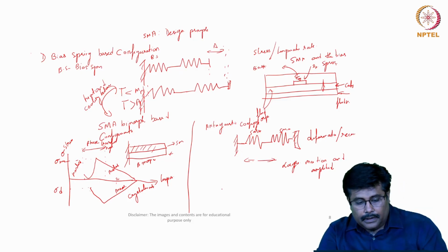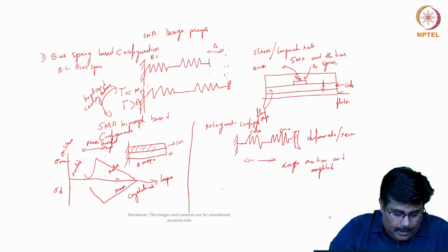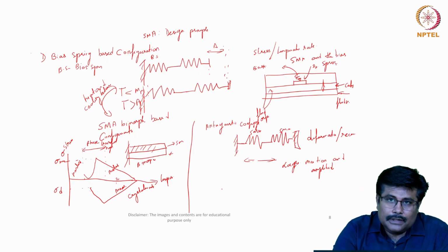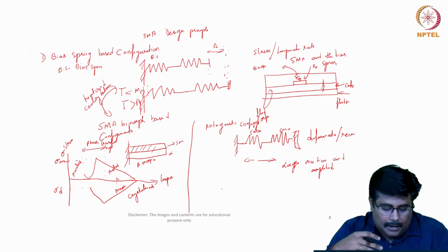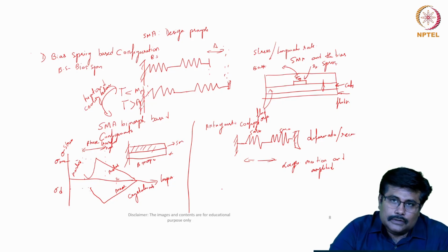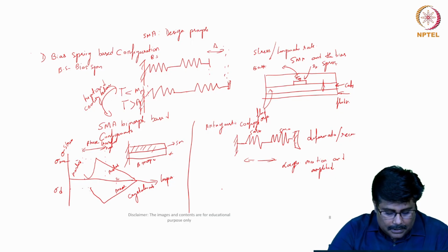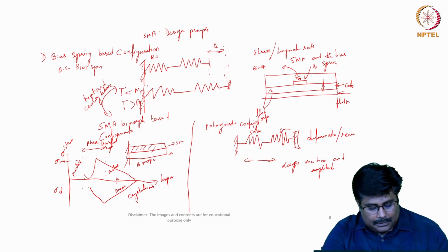So when we try to illustrate this figure, this is a kind of a NiTi film deposited on a Si substrate. At the deposition temperature considered, the film is amorphous, no crystallographic structure is formed. To be functional, an annealing step is required, which is realized by heating the film, typically by 700 to 900 Kelvin. Upon heating, due to the difference between this transformation film and the substrate, a compressive stress gets built. So upon crystallization at a temperature TA, the stress is relaxed and the film is under tensile on cooling.